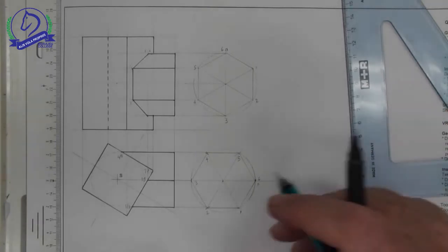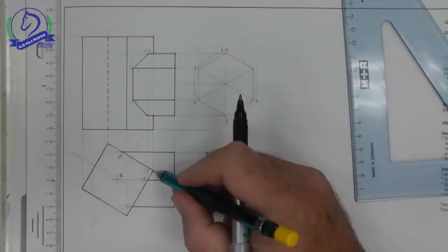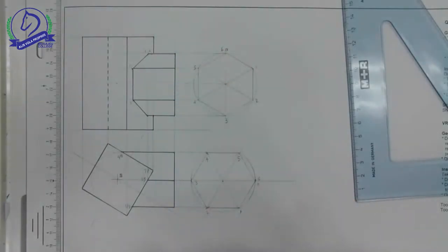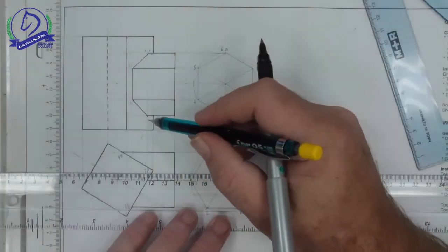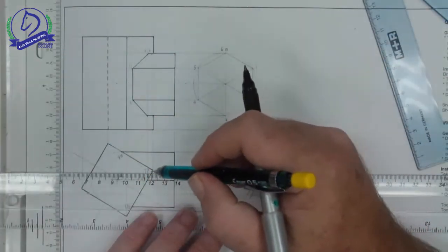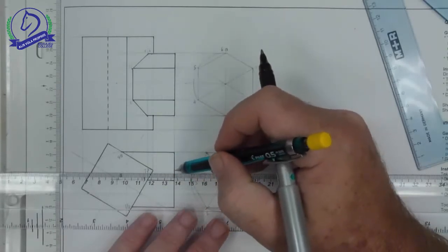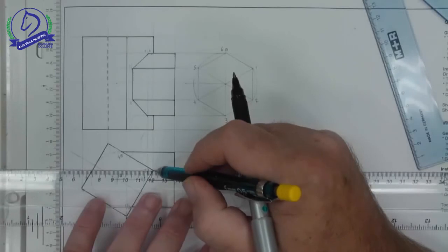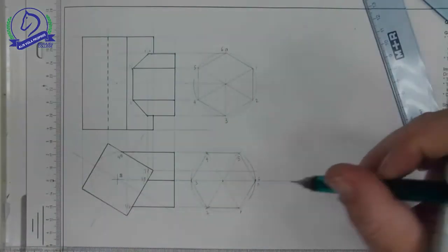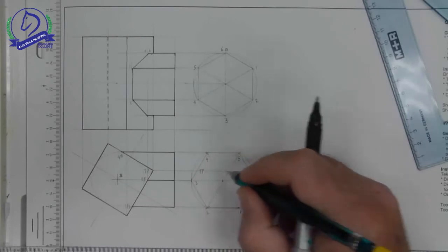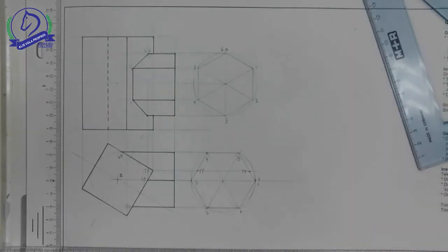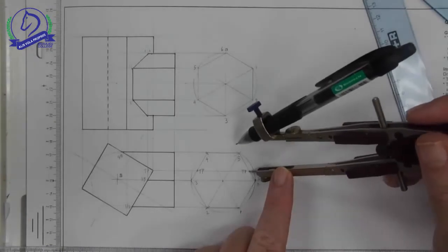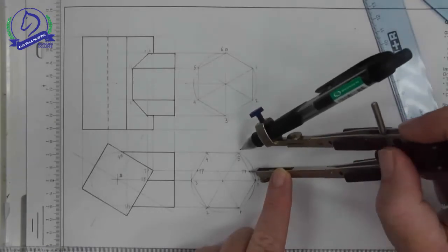So much like we've done before, what we're going to do is take where the turning point is. So that's on that edge. Now where does it hit? Because our branch pipe is horizontal and parallel to our base, we can't project where it touches on the side. So what we need to do is use our auxiliary view. So we take that across to our auxiliary view to get the turning points on the auxiliary view. Then we take the distance in our auxiliary view. So I'm going to measure from the turning point to 2.5 with my compass.